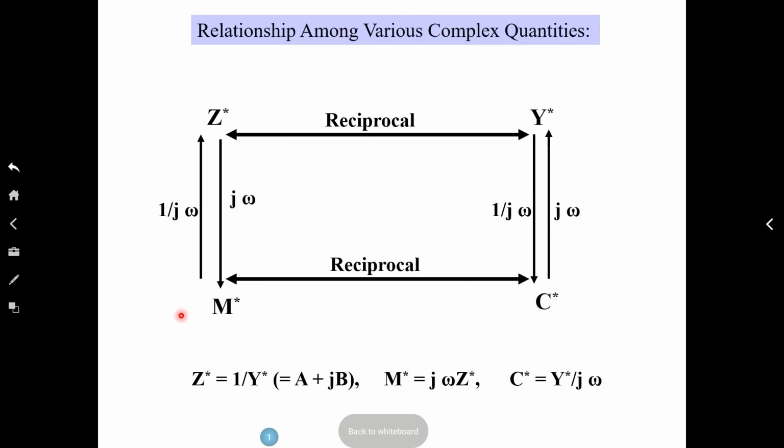You can do electrical modulus. So you can see how to convert. If you have the impedance value, all you have to do is multiply by C0 omega. That will give you the electrical modulus. So you can convert your impedance to electrical modulus and plot imaginary modulus versus real modulus and create a plot called a modulus plane plot.